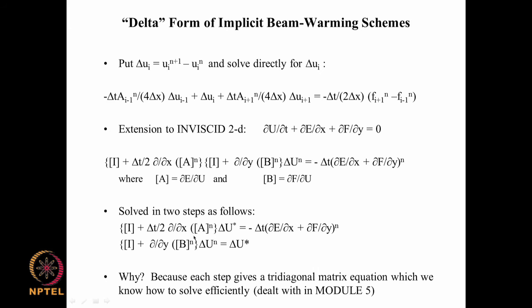So in that sense, this is an evaluation of the nonlinearity and coupling based on the previous time step values, and therefore this is called lagging. This particular contribution of the overall equation is based on the previous time step values, whereas this is based on the new time step values.